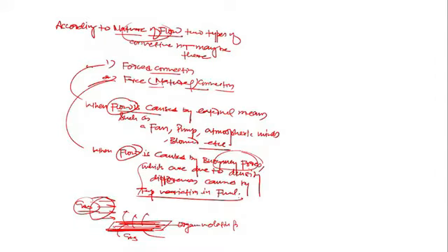As we move away from the surface, there is a velocity boundary layer, and there is also a concentration boundary layer, because any fluid layer on the surface will have CAS, and as we move upward, the concentration decreases. This C is a function of y. So here CAS and further up the concentration decreases, yes or no. But the mass transfer on the surface is only by molecular diffusion,